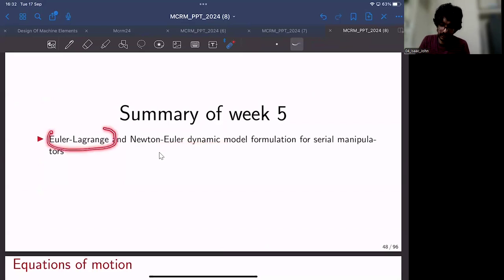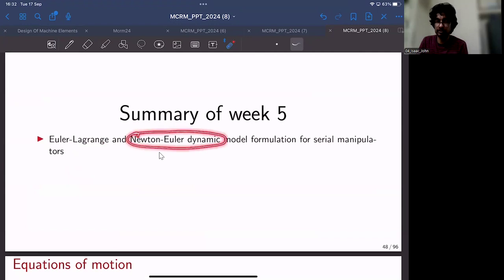So this is actually an energy-based scheme, much easier to derive for smaller robots, but Newton-Euler is much more comprehensive, because Euler-Lagrange only estimates the torques or forces along the actuator axis, but Newton-Euler gives you all 6 components of forces and torques, along the actuator components, and all the other directions, which correspond to the reaction forces. Those forces are also estimated using Newton-Euler